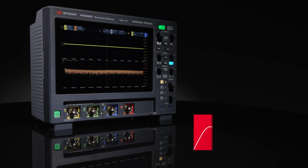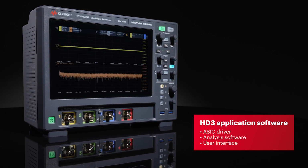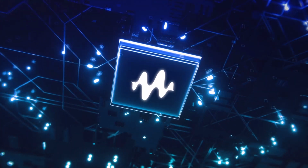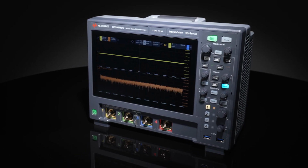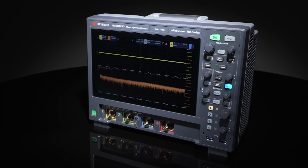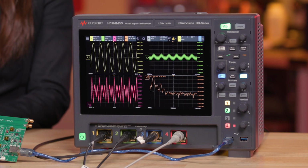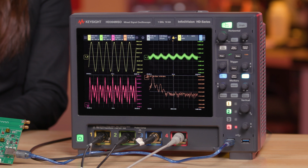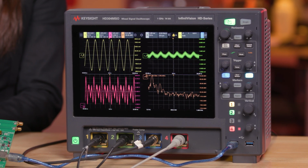Thanks, Bob. The HD3 application software consists of 3 systems, including the ASIC driver, the analysis software, and the user interface. The ASIC driver software is designed to turn on the full feature set of the ASIC. The analysis software utilizes the software from existing Infinivision products and is designed to support turning on ASIC features, taking advantage of 14-bit ADC, deep memory, and digital triggering, to name a few. Finally, the user interface software is developed using a modern GUI, giving the HD3 products a new look with no limitations on future editions. All 3 of these systems support the new custom ASIC technology.